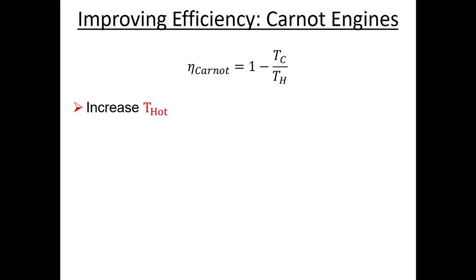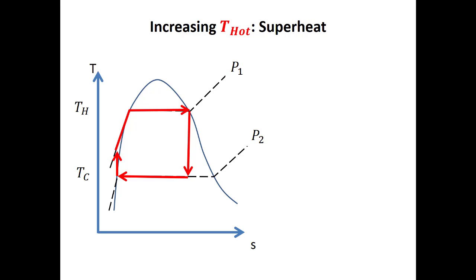So when we look at this Carnot efficiency, even though it's a very simplistic model, right? It's this ideal engine that actually can never exist in real life. But if I look at this and I say, well, if I could increase T hot, I'm at least improving the maximum efficiency that I can get, which probably leads to the improvement of real efficiency. Or I can reduce T cold, right? So from this very simple equation, we can see as engineers, here are two potential things that I can try to do to get better performance, right?